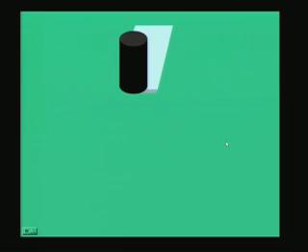So, constructive solid geometry, continuing on that, if you have a look here, this is what I want to generate. Let us say if I want to generate this particular structure, what does this particular structure say? Well, I am seeing a cylinder, a black one in front, and I am seeing a thin rectangular plate with a small height, and they are not only adjacent to one another. In fact, we have to visualize that the plane is coming out of the cylinder. Of course, the cylinder can sit on the plane, it depends upon where you want to position them, but you should be able to generate a scenario where the plane and the cylinder are mixed at the base. That means one object is entering into another.